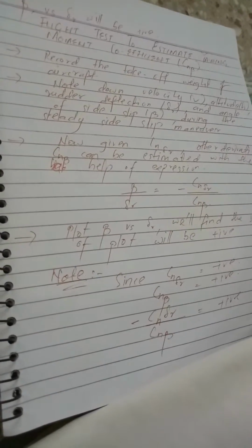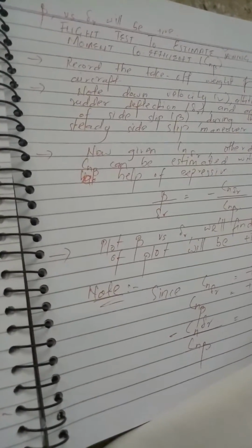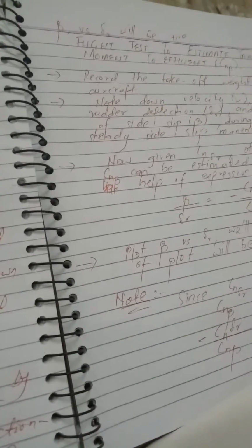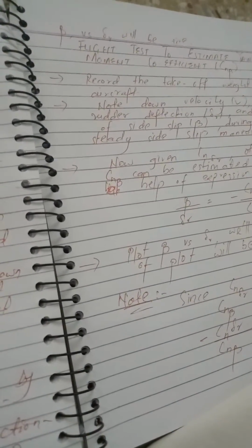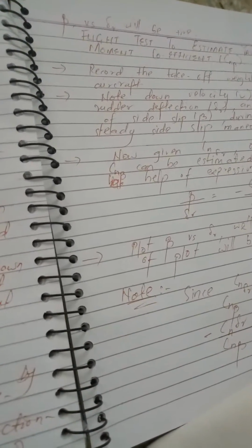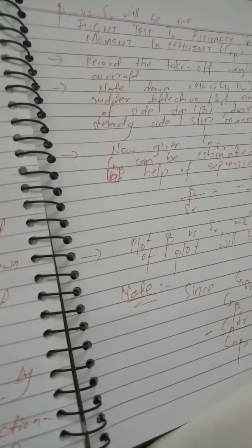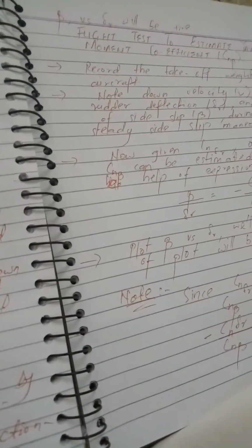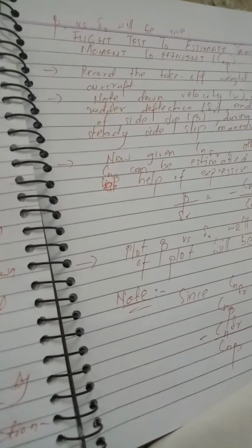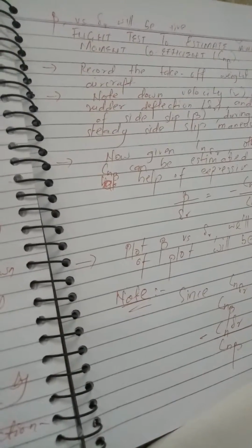So that is all together in this video. What we have estimated is the yawing moment coefficient, and the yaw moment is being counteracted by the rudder. The rudder is required to counteract this Cn of beta, and also Cn of lambda A, which is the stability because of the aileron.